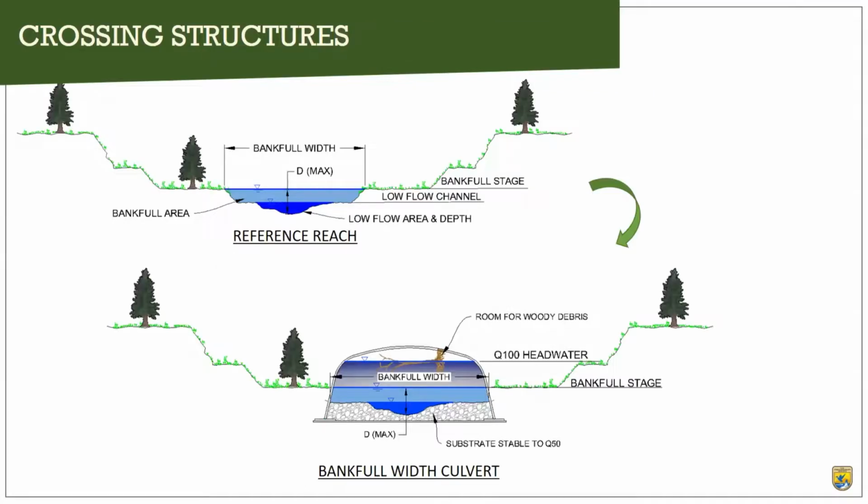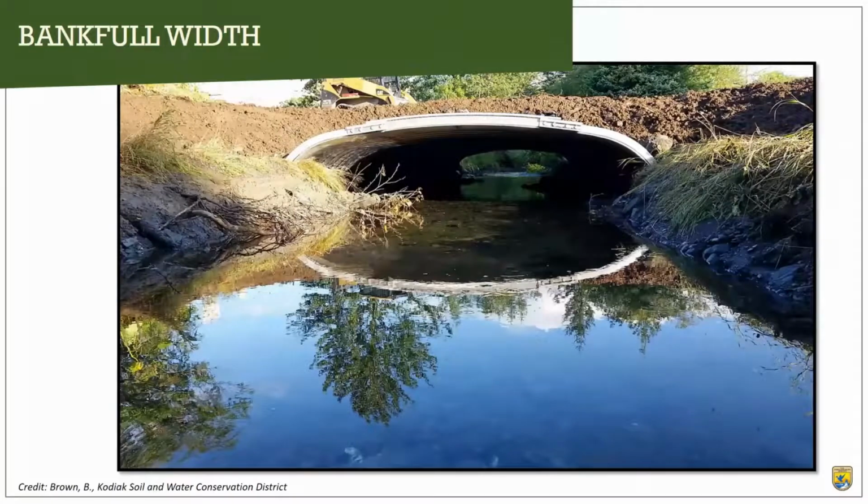We might also install a bankfull width culvert. So this is the minimum culvert width for a geomorphic design in order to maintain those bankfull hydraulic dimensions that we talked about. And this helps us maintain sediment transport continuity as well, as we've also talked about.